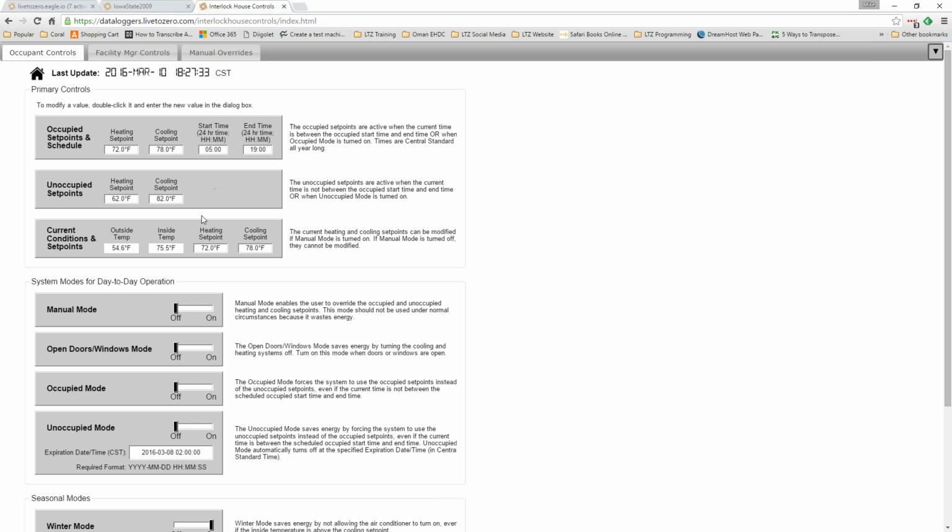It's not going all the way down to 62. It's maybe only going down to 67, 68. So the building doesn't have to heat up as much in the morning when you need to get back to 72. So one controls question here, ideally the way this would work is that you would say, okay, well, how long will it take to get the house back to 72? And set your what's called the setback temperature schedule to the appropriate time so that the building has just enough time to get back to 72 degrees.